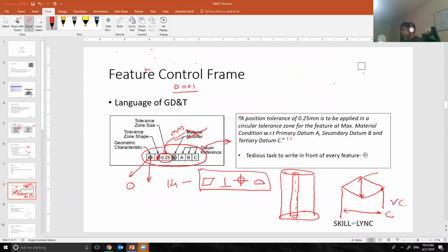Right. That's a very good question. And believe me, when I was on my first day of the job, I had this exact same question. And the answer is actually, there are some specific tolerances based on the supplier that you're working with. So in general, let's say an engine mount, the A datum will have a flatness of 0.25. Okay, this is a generic tolerance used for any machining part or any machining surface. I can give the tolerance as tight as 0.01 millimeter as well. But then the supplier will raise the cost like $10,000 or something like that for the tooling.